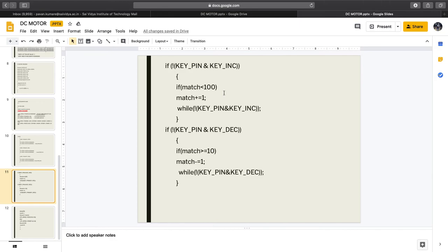And in our program we are not using pulse width modulation. Basically the working principle, if you see the controlling part, the DC motor can be controlled with the concept of pulse width modulation, but we are not using pulse width modulation here. We are just using some increment and decrement operations to increase and decrease the speed. So let's see how this program works, or a sub function.